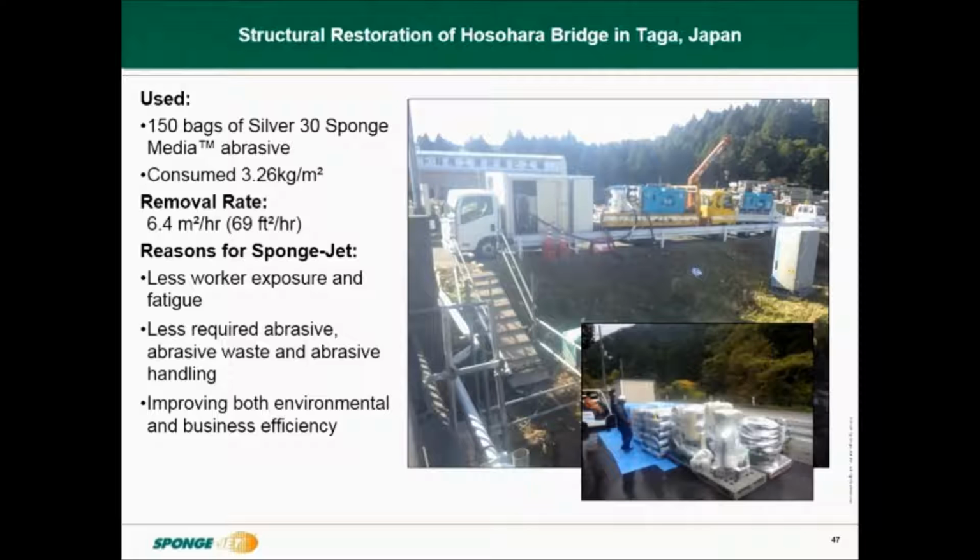They offered a removal rate on this project of 6.4 square metres per hour, and when we do the calculations on that to blast 832 square metres, that shows us that it took them 130 hours, around 21 six-hour blast days.